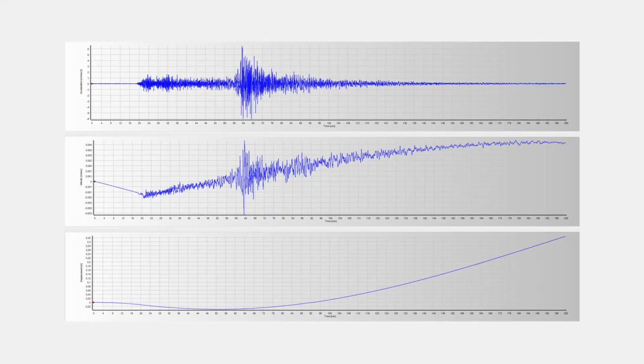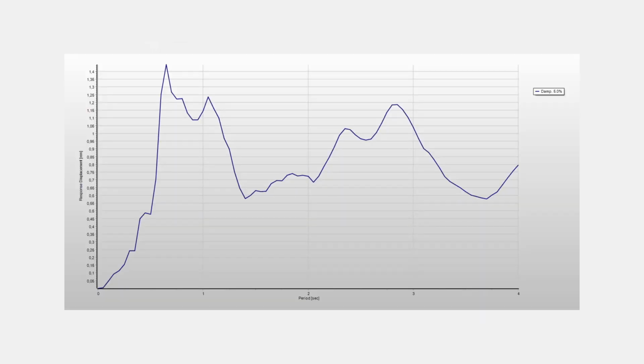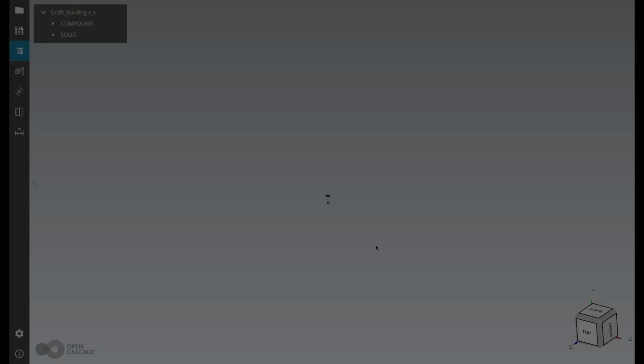After generating a frequency response on SeismoSignal, the displacement for the maximum period of 4 seconds was taken and scaled to 15 mm and 30 mm. This can allow us to accurately set up external forces on the structure when performing a SolidWorks simulation.